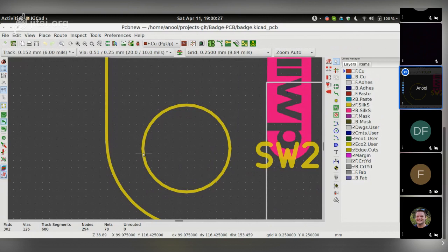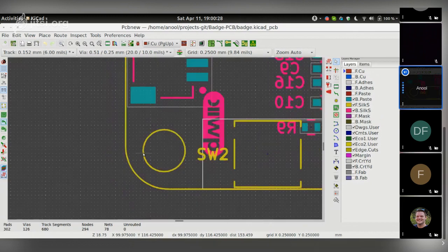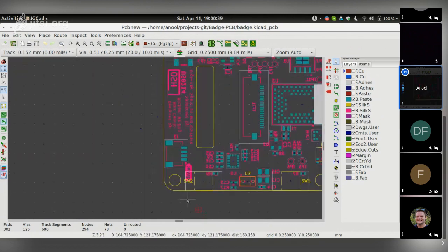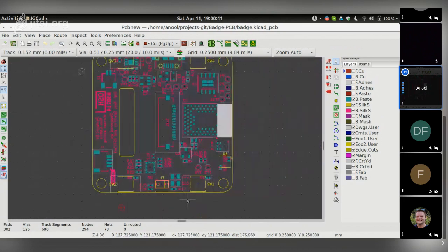And this means that you lose information on certain important things like where is the center of this particular circle or where's the center of this arc. So without that, once you try and get things from KiCad into FreeCAD, let's say to design enclosures or do any mechanical work, the lack of that information becomes pretty apparent, because if you can't fix precisely the center of the circle, it becomes difficult to design an enclosure around it, for example.